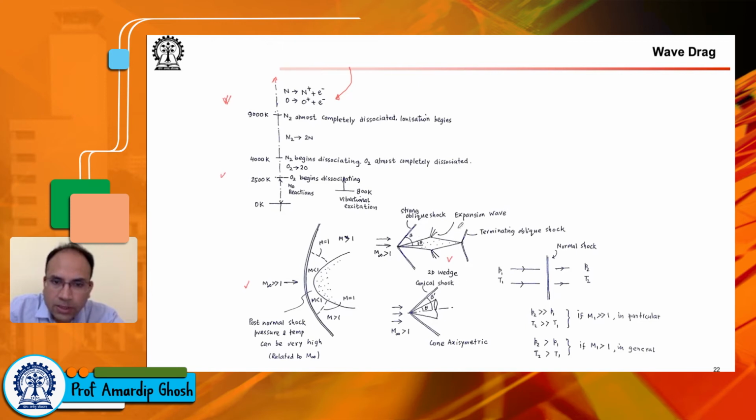Okay, so here is a wing cross section in supersonic flight. Now see, unlike your subsonic wings that look something like a streamline shape with the blunt leading edge and cusp trailing edge, your supersonic wings are typically of these kind of sharp profiles. And what happens is a supersonic flow, when it deflects, creates shock waves or expansion waves. We will study these things in detail.